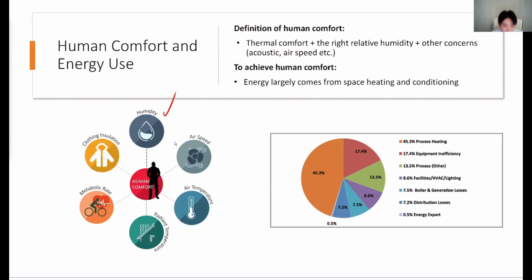That radiant energy basically comes off our equipment, our internal furnishings, even the sunlight. These radiant temperatures all affect us. They make us feel either hotter or cooler, right? So these two temperatures together, we need to consider them to be at an optimal level so that we actually feel comfortable. And the last two factors actually depend on us as occupants, because the metabolic rate and the clothing insulation, or the clothing level that we have, is entirely up to us, right?